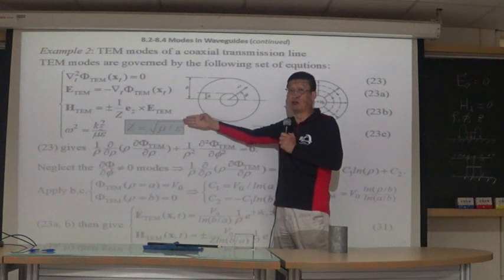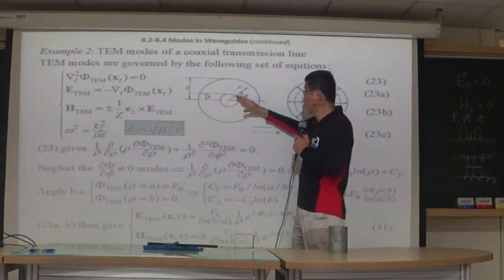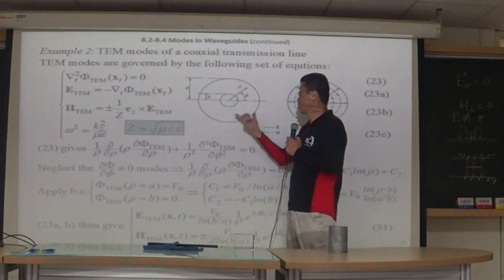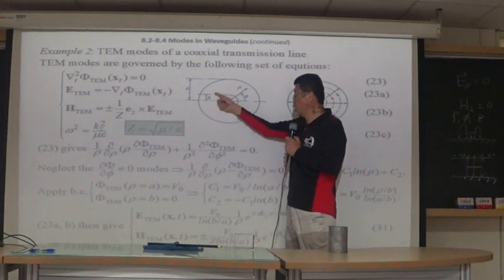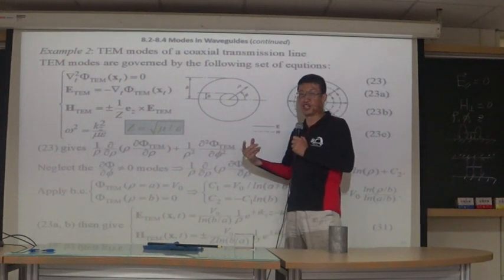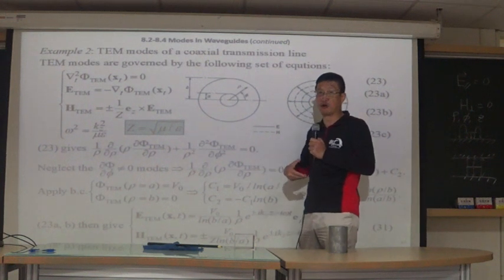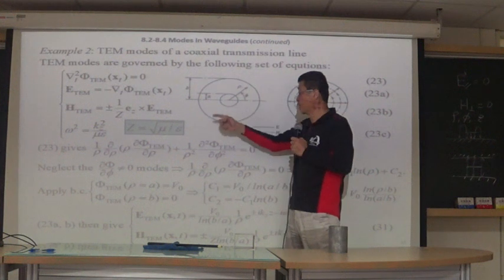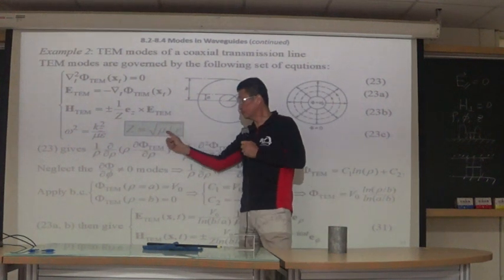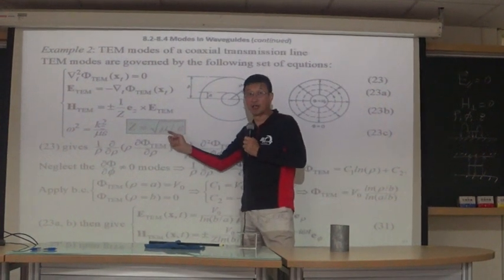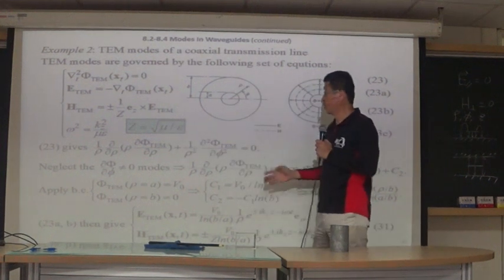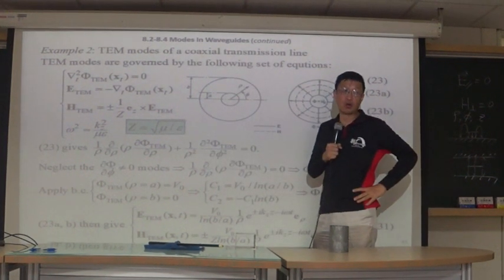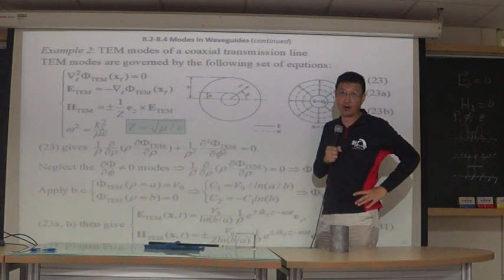Z actually depends on materials only. So how do we support the inner conductor? The inner conductor cannot be supported in air, so you need some material to support it. Here we use a material to be determined. Actually, we prefer a material called Teflon.